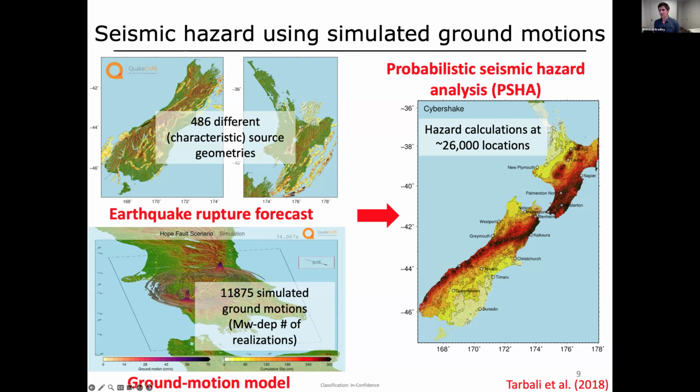Possibly, but not easily, in the sense that, if it's hybrid, where are the boundary conditions? Probably the one location that the hybrid can be useful is if you have, for example, a downhole array, then you can simulate the result to the bottom of the array, and then use the actual array directly as a seismoscope, so to speak. But there again, it comes back to one of the things Thaleia was mentioning: even with things like downhole arrays, we're assuming 1D wave propagation, and increasingly the evidence is showing that in many cases that's probably not a good assumption. In fact, we may have had 2 decades of work focused on 1D site response because of downhole arrays, when it actually led us astray a little bit from exploring the real 3D behavior that we typically find actually happens.